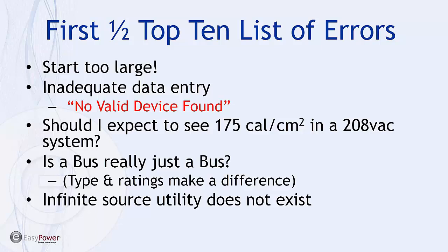And so what I recommend, especially for a very first-time beginner, is to start with a very simplistic one-line diagram that shows your source, whether it's utility, batteries, or generators, and then a single connection down to the lowest load that you need to label, and make sure that you're aware of the mechanics of the tool and the data that's required to generate the outputs that you want.